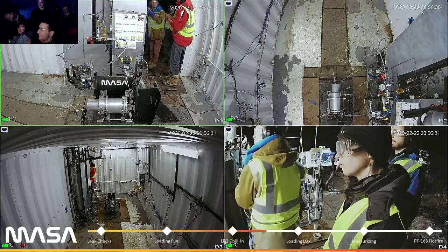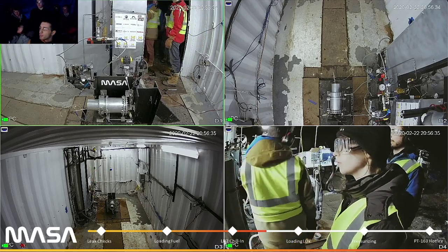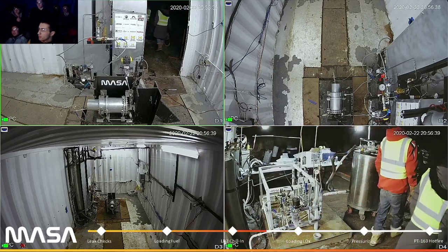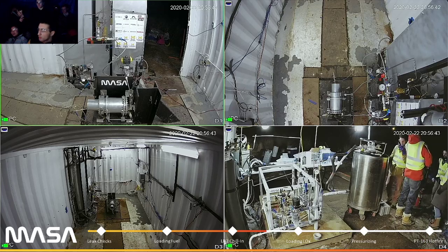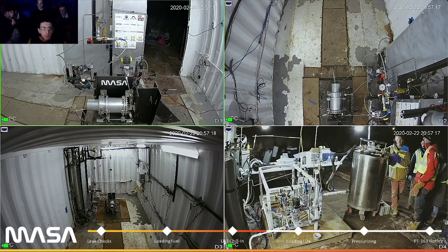Should we try fuel? No, fuel's already through the LOX line, so we can't do fuel now. Oh, yeah, it's full. I forgot. We're gonna just reject the tank quick. Can you fill CNG to 100 psi target and box tank 20 psi target? Okay, we're good. 20 psi in the tank.